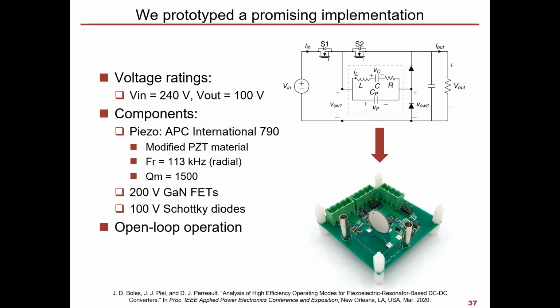Now, that's not to say that the piezos couldn't one day, but again, there's that scaling property with the magnetic component: as we go up in power, a large increase in power is just a small volume increase, which is good for high power applications with magnetics. So if it's high voltage, high power, I think the magnetic solution is probably going to win. If it's high voltage, very low power, I think the piezoelectric transformer could certainly compete pretty heavily.